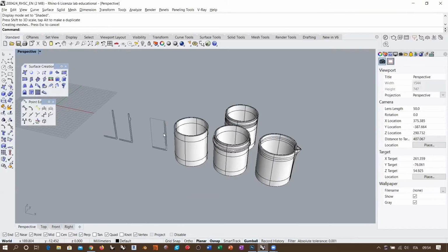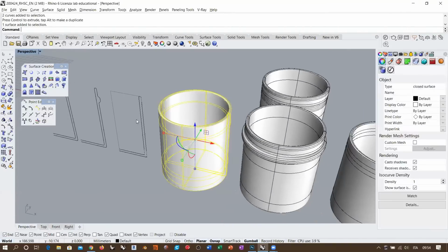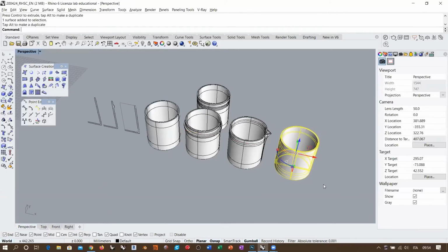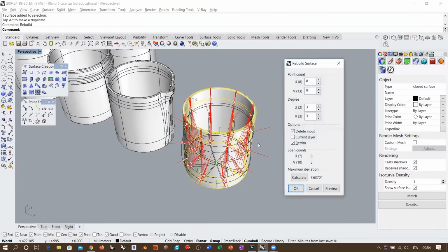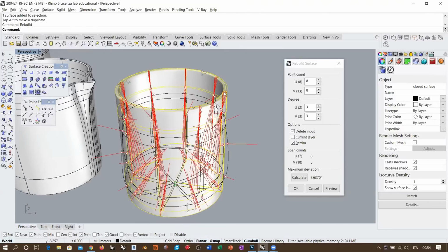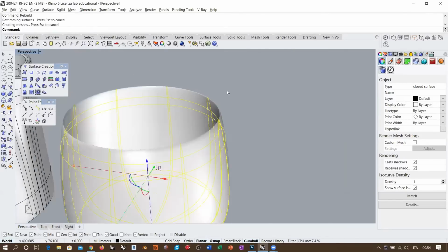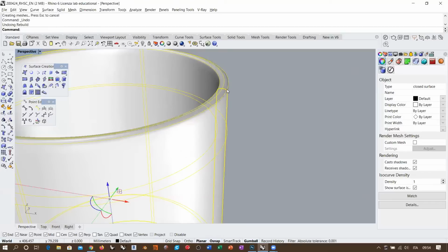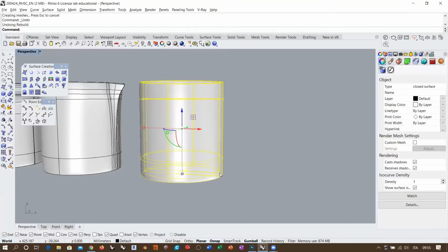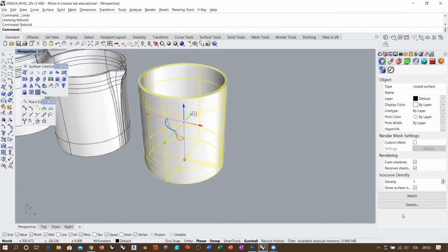You see that I never recommend rebuilding things as a first option, because rebuild is a dramatic operation. Okay, so of course I can take the original surface that comes out from the standard rail flowing along the circle, like copying this, and I can rebuild this surface. Now, of course, in order to maintain this particular shape, which has no creases, it is perfectly smooth, but it has very sharp roundings here at the top, okay? And also we have 90 degrees here at the bottom, more or less. So in order to rebuild this, yeah, question.